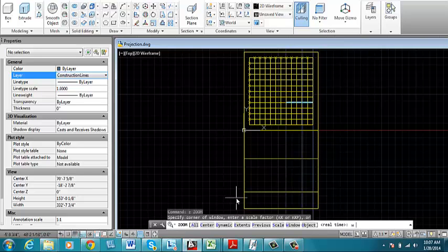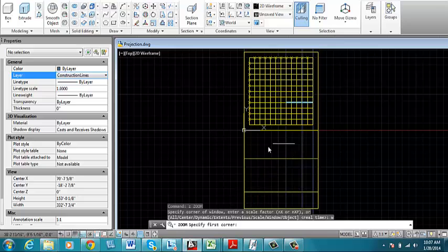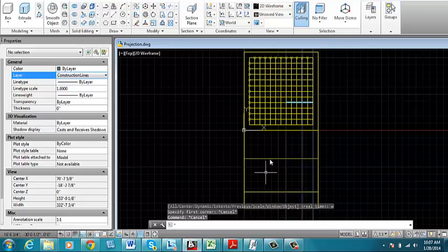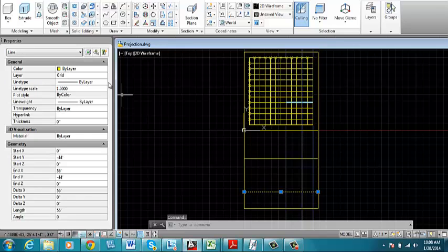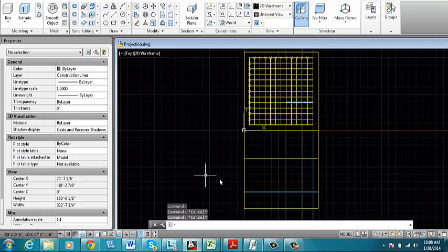Okay, so now as I mentioned, this is going to be an elevation and this is going to be a section drawn right here. Now the difference between an elevation and a section is simply the placement of the cut. Anything that is cut is graphically shown with a heavier line. For an elevation drawing, the only cut line is the ground line. So I'm going to take this line and put it on the cut layer. So it now appears in cyan.